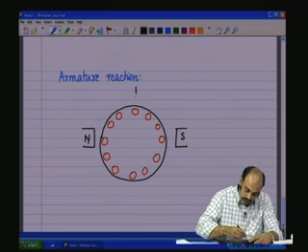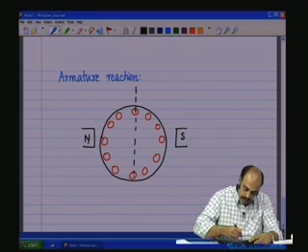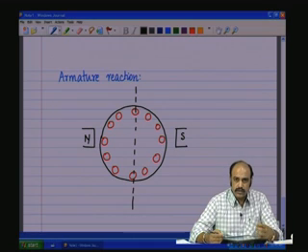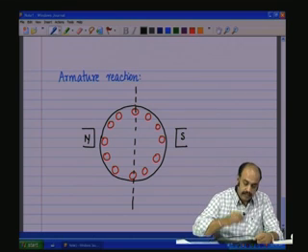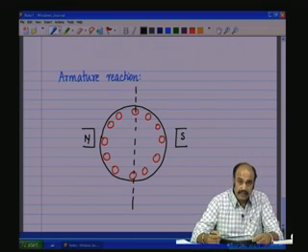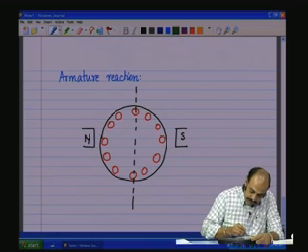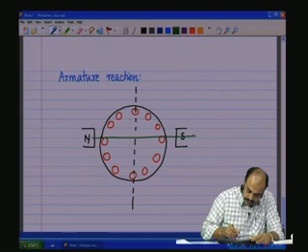And this orthogonal plane was supposed to be our neutral zone, where there was not supposed to be any induced voltage and thereby no induced current, because at this point the flux is equal to 0 in that direction. Now there is a flux, north-south flux, which flows in this direction.